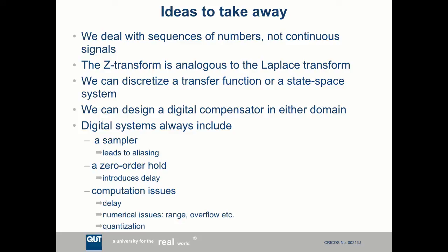It's just whatever's convenient. If the system's only got one input and one output, you might as well treat it as a transfer function. You can do it in state space, but it doesn't buy you anything. If it's got more than one input or more than one output, or both, then it's much more convenient to consider it as a state space system. Yeah, a simple one input, one output, do as a transfer function. It would be easier.